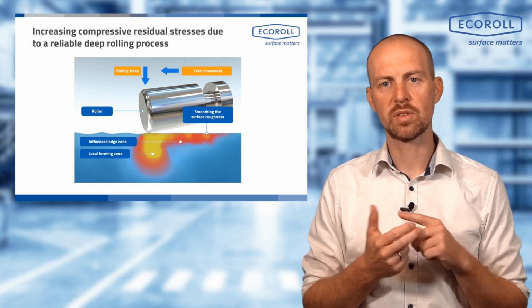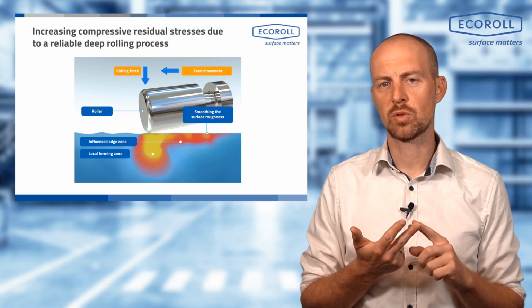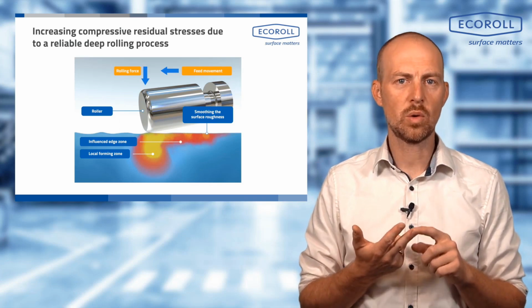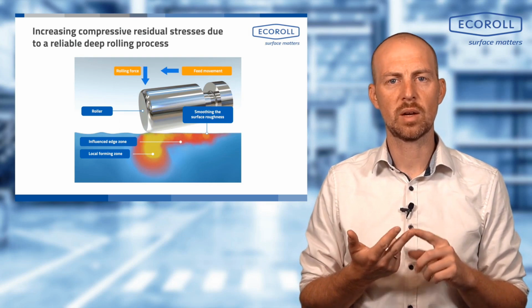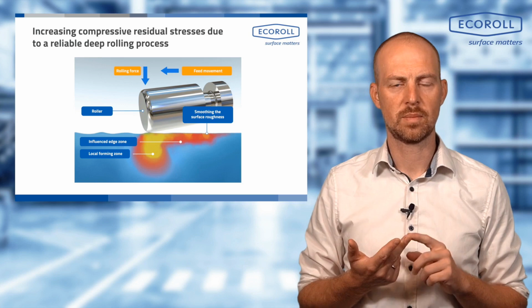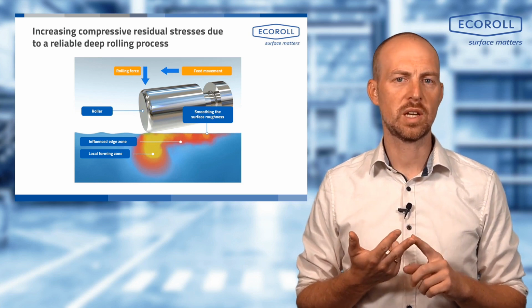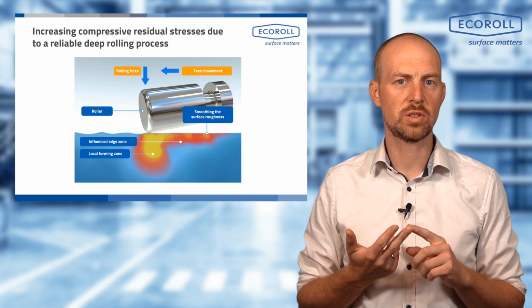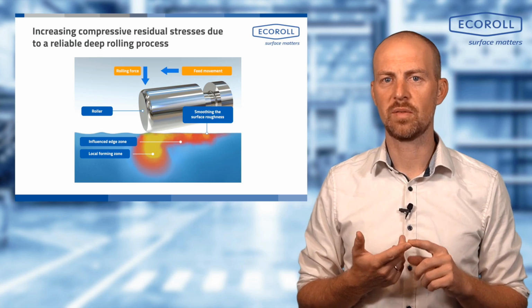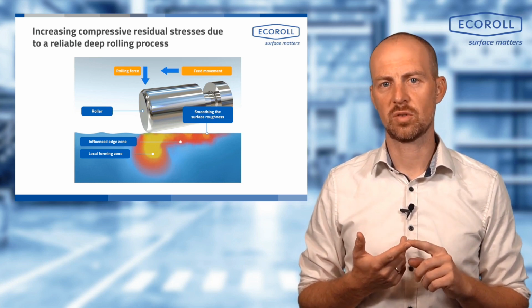The geometry and also the feed are actually well controllable through the process. The feed rate can be entered in the NC program, and it is fixed. If nothing is changed in the program, this feed rate will remain in effect. The roll geometry is also defined. All manufacturers, including us and all others, naturally check our rolling rolls for the corresponding geometry. This means that the rolling roll and the contact geometry are also very rigid parameters that are generally not changeable by the process. The third parameter, the rolling force, on the other hand, can change during the process.